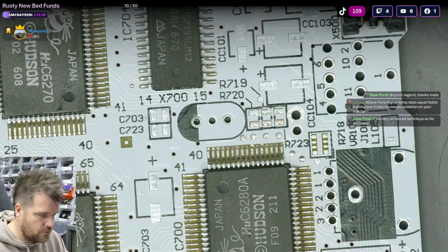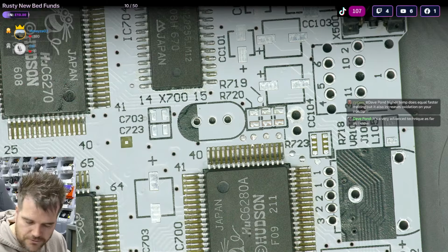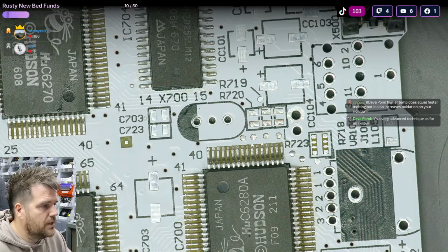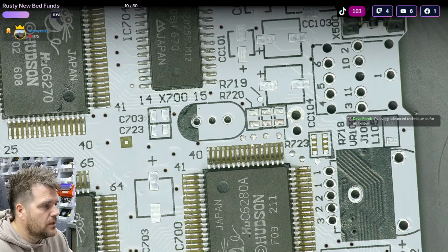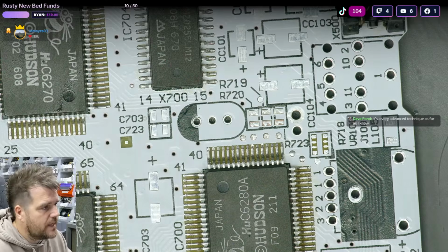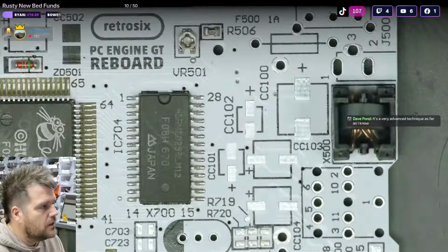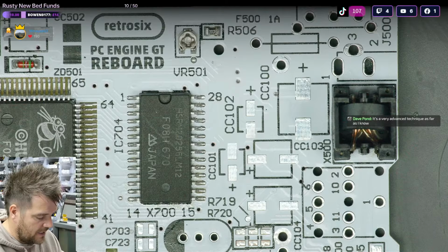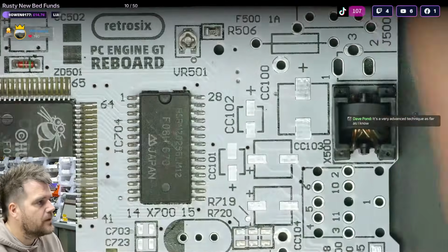I used to run it at 420, but the only downside is at 420C the tips burn out because that is quite hot. But same with the hot air, I work hot. Everything I do, I pretty much work hot and fast, if you will. I'd guess that's probably what people would class it as.